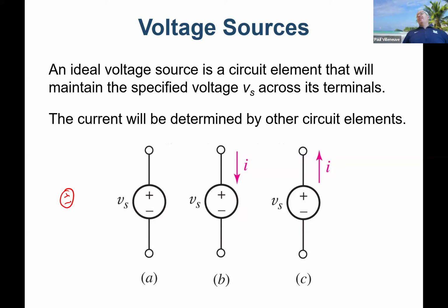You put the voltage source, that's ideal, and then normally you put a resistor with it, right? And as you increase the current out, the voltage drops. So the more load you draw, the lower the voltage is on the terminals.